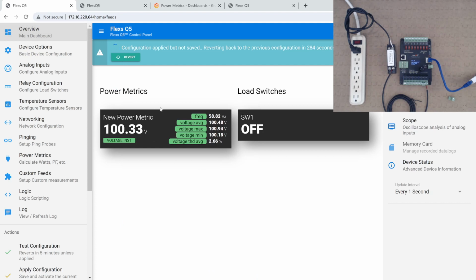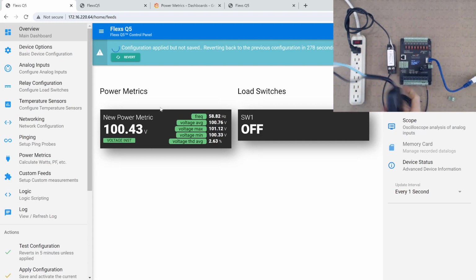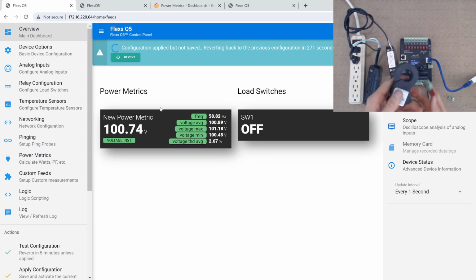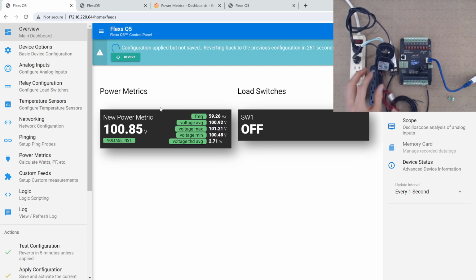So what I've done is I've gone ahead and taken a power splitter and just exposed some of the leads here for a test. So we can plug this guy in right here, and then I have a current sensor. So this is just a clip-on AC current sensor. There's lots of shapes and forms of these that come from lots of different suppliers. This one here is good up to 200 amps, so we can just clip that onto one of our wires.